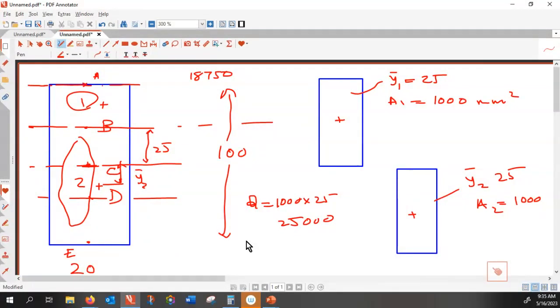So why does the shearing stress become maximum at the neutral plane? Because the Q for that is maximum. Everything else is the same. So for one given cross section, the shear force doesn't change. You look at the shear and bending shear force diagram, that is only a function of X. It doesn't depend on Y. So V is the same.